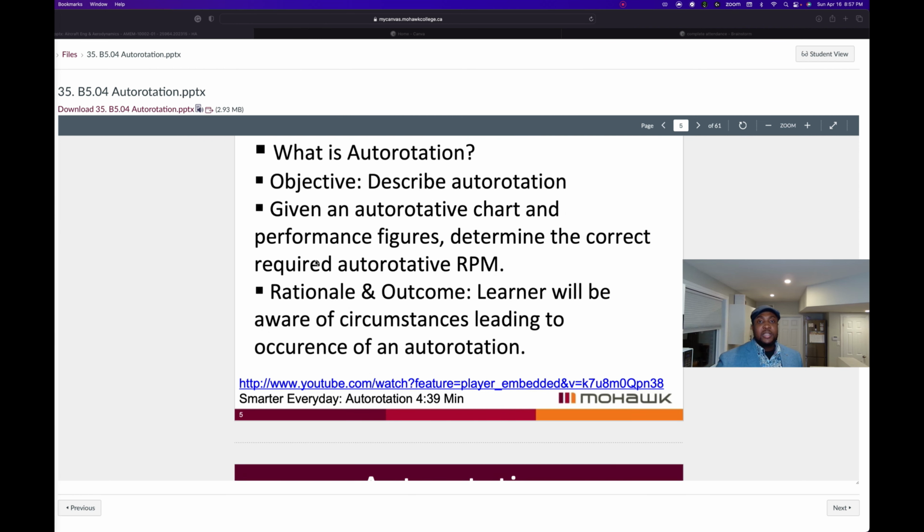In this case, you don't have sufficient forward airspeed for the altitude that you possess. The shaded area on the left shows the areas where successful auto-rotation is not likely to be possible in the event of engine failure. So do not operate the helicopter for continuous periods of time in this area at all. If we take this position right here, where we have a height above ground of about 300 feet and an airspeed of about 20 knots.